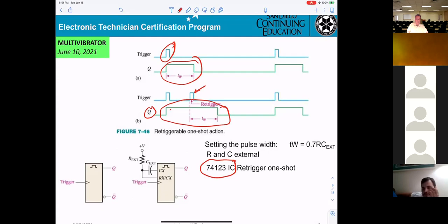Basically, if you really want to understand, then we can do the lab manually. It's easy to make the connection, and use an oscilloscope to verify. Then you can change the R and C and see how long the pulse coming out will be.